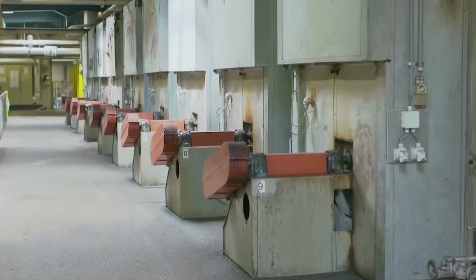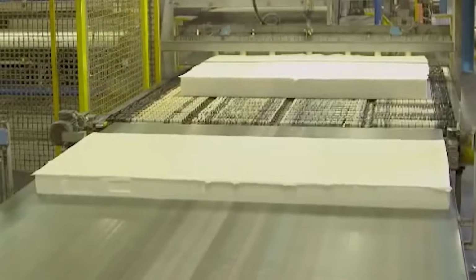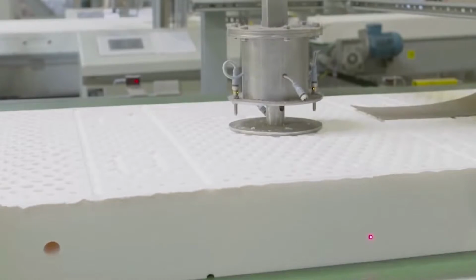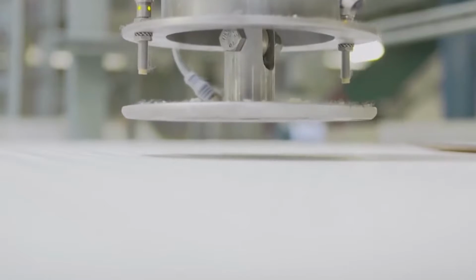The finished foam is poured into special molds and evenly distributed. Then a vulcanization process is carried out when, under the influence of high temperature, the foam turns into a soft and elastic latex block. Pay attention to the holes. They have different diameters and determine the stiffness of the mattress in different areas.